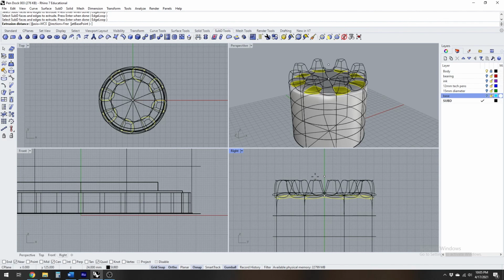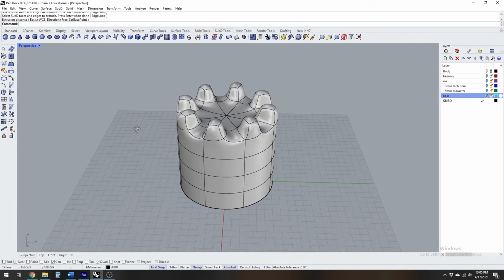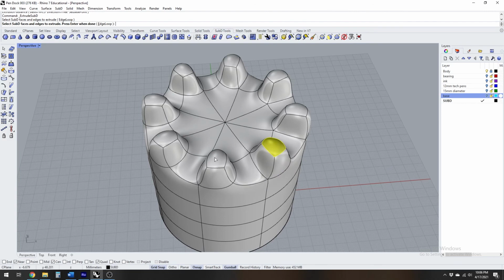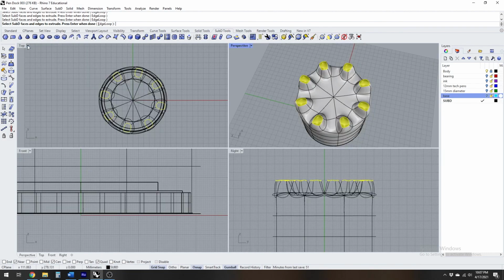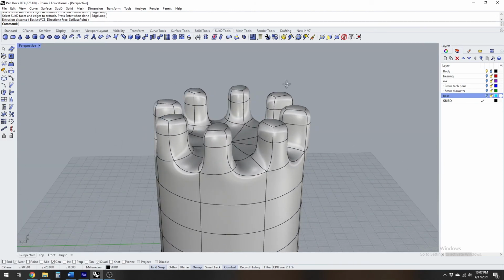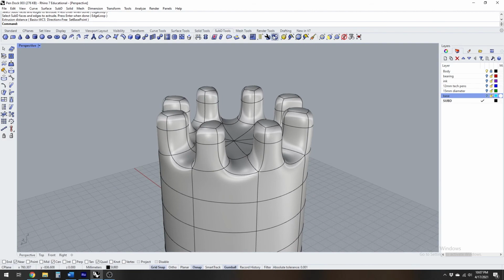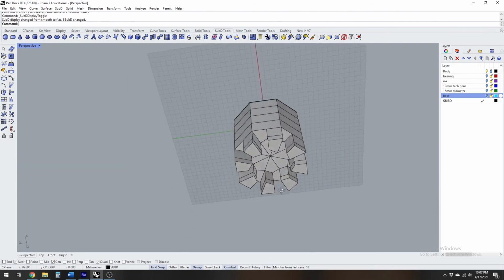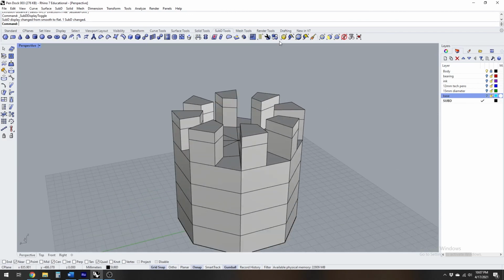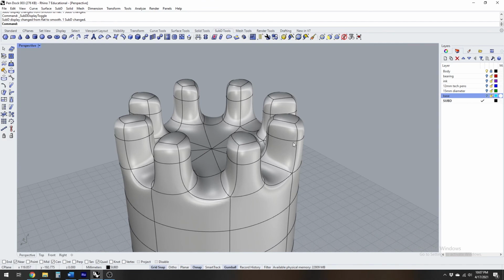And when we left click this selection, you'll see that it's built out surrounding surfaces and also done the blended tangential relationship between those new surfaces. Really butter smooth. Now I want a little more definition at the edge here, so we are going to do yet another extrusion. And you'll see that everywhere I have vertices and lines, I have more geometry. So now those protrusions are a bit more crisp, and swapping back into our toggled mode, you can see that they are trapezoidal and that they have an edge loop right near their edge.